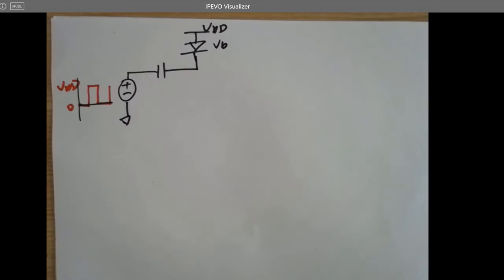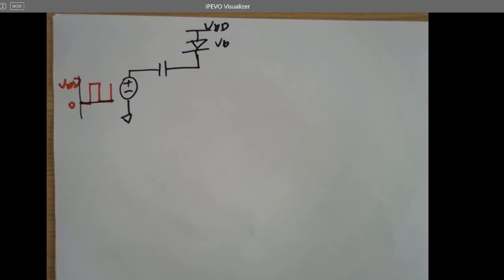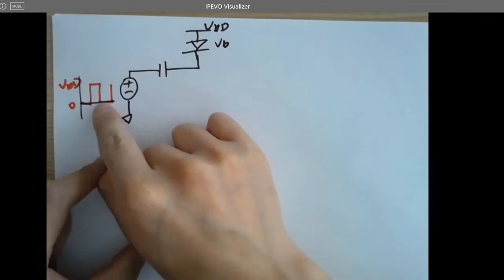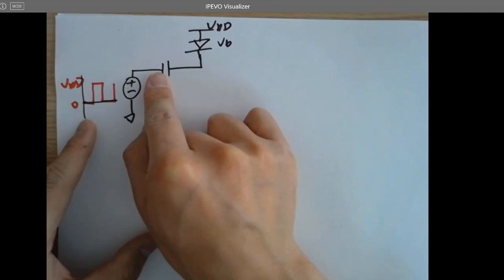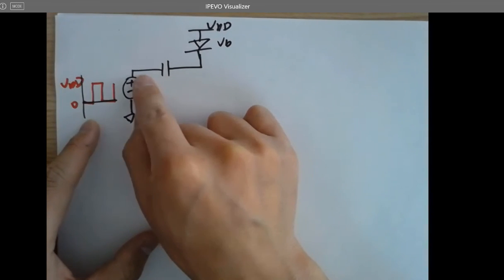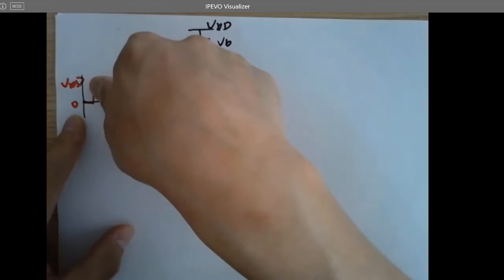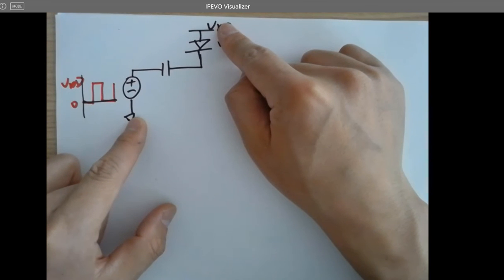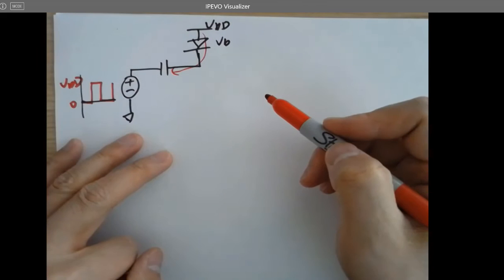When you are analyzing a circuit like this, you just want to have an animation in your mind. Since the oscillation is fast, it's not a steady DC voltage. So the charging and discharging of the cap is always happening, and there's current flowing in and out of the cap. Whenever the voltage is 0 at the first cycle here, here is high, here is 0, you get a voltage potential drop, right? What's going to happen? It will be charged through here, so the current will be dumped into the cap.